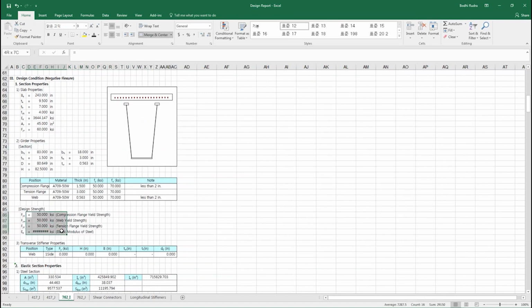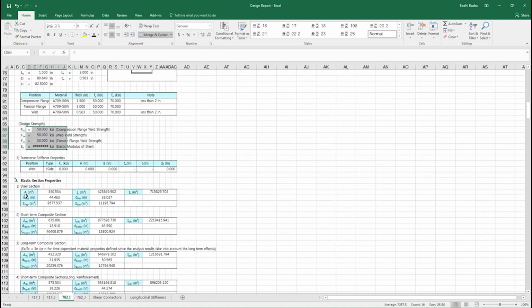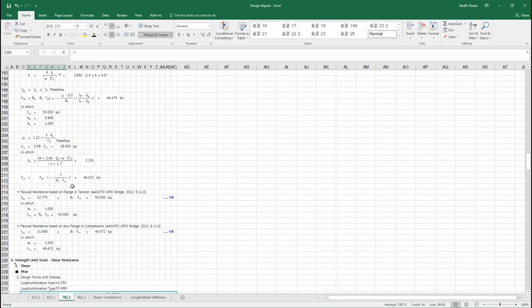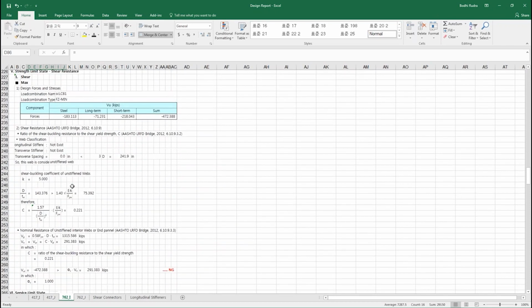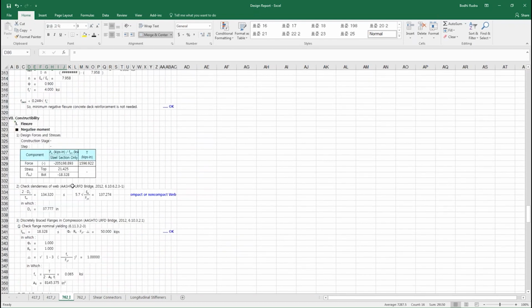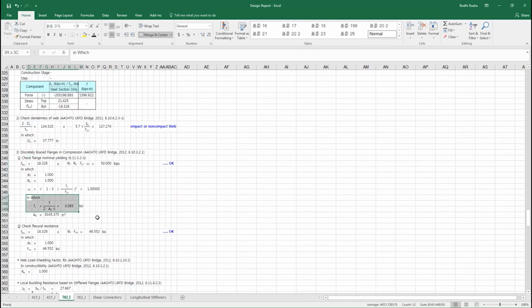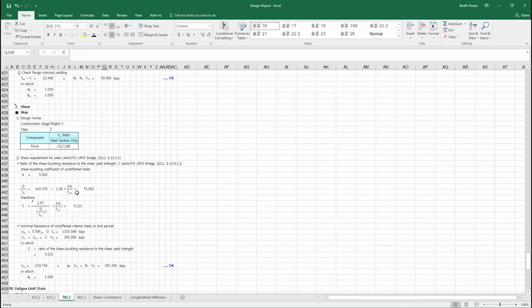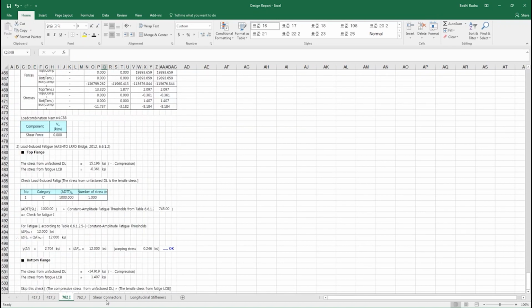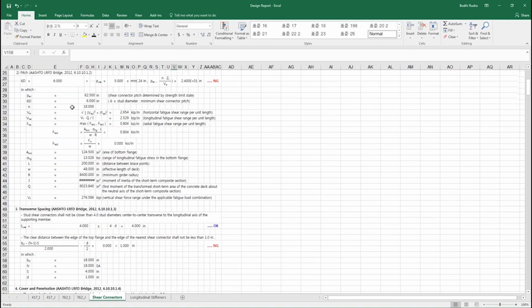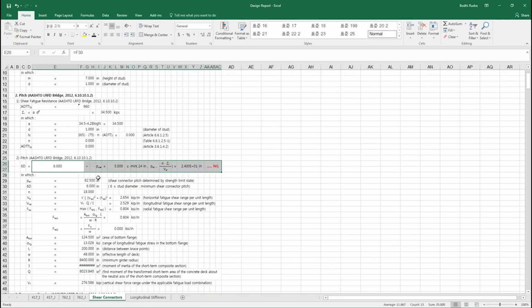And then we have design strength, transverse stiffener properties, flexure properties. So it checks each and everything inside the code and provides you the information. Here it is checking for Saint-Venant, the Saint-Venant shear force that it is checking. For each and every thing that it checks, since we provided shear connectors for only a few elements, it is showing that a few things are not good.